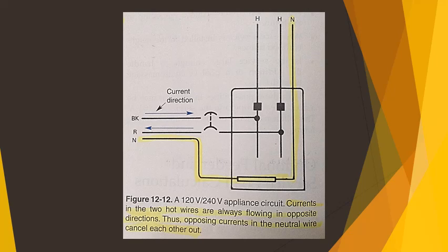Balancing circuit loads. When planning the hookup of branch circuits and feeders to the main service panel, it is important to keep a balance in the load between the two hot wires in a three-wire system. Remember that the neutral wire in this system is carrying the unbalanced electrical load from both hot wires.